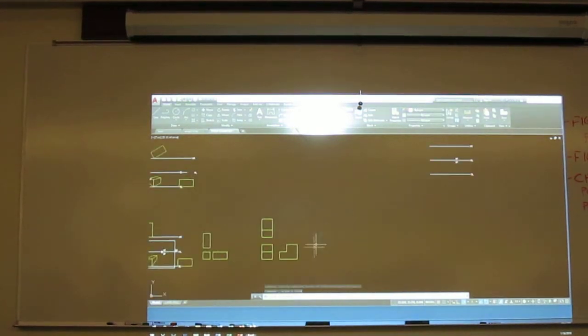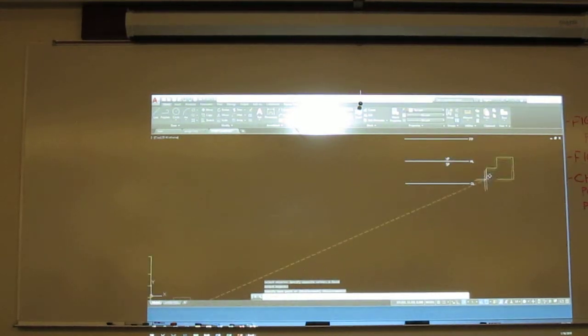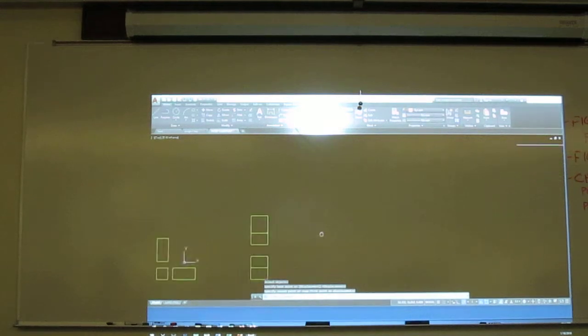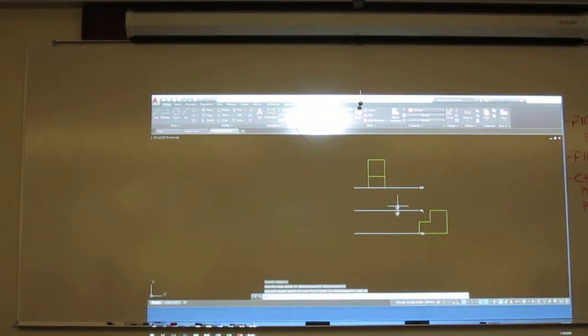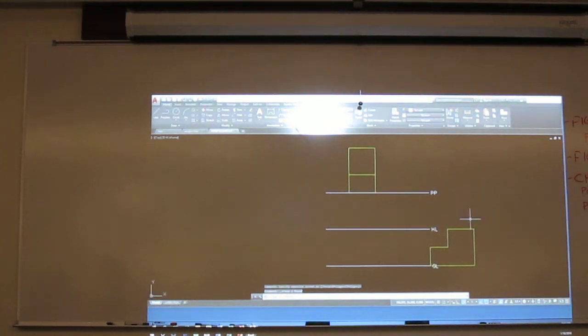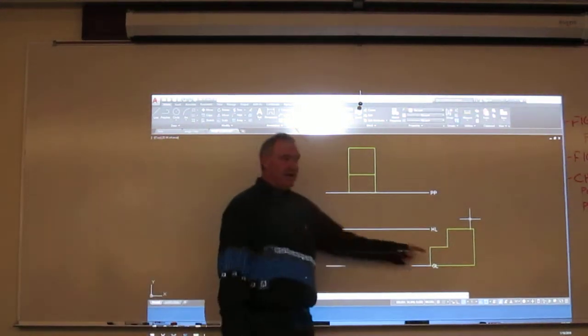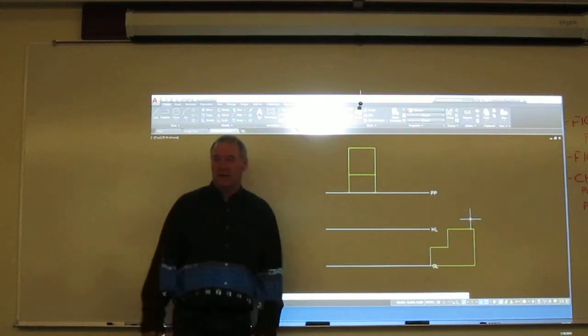And then set it up. So I'm going to put my right side view on the ground. If you get to this situation where you've got the ground line, horizon line, picture plane, and your two views you need for this object, which would be a view that has height, the right side view works the best, and the top view set on your picture plane as such.